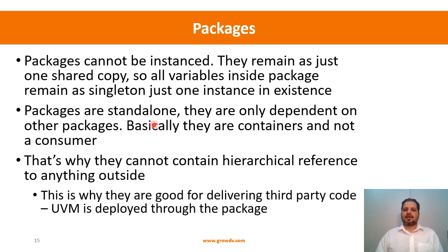Another point is that packages are standalone. What that means is they are only dependent on themselves. In a way, you can import other packages, but that's it. This is because they are just containers. They do not consume. For example, a module is, in a way, a container and a consumer. If I declare a particular task or function within a module, then I can put an initial block and call it as well. But that is not how packages work.